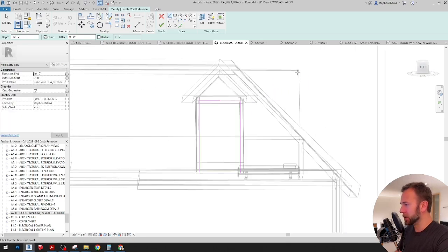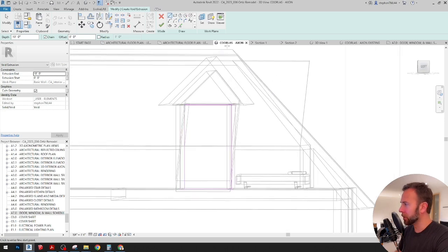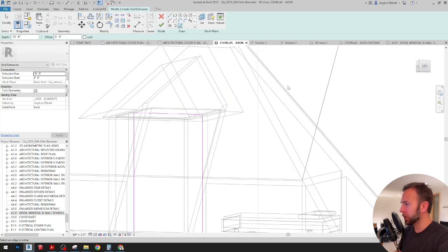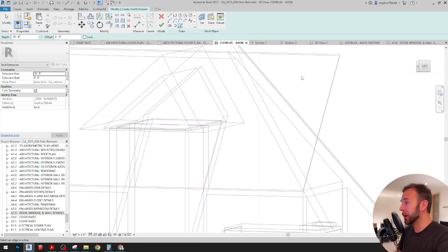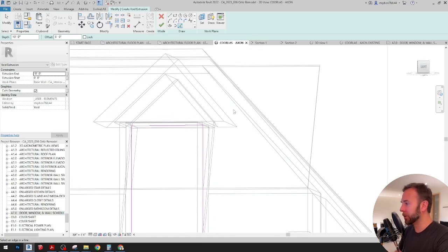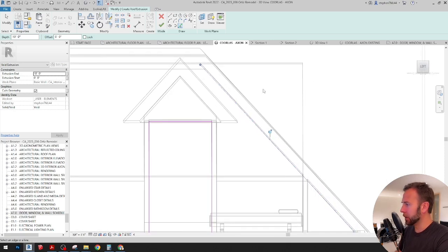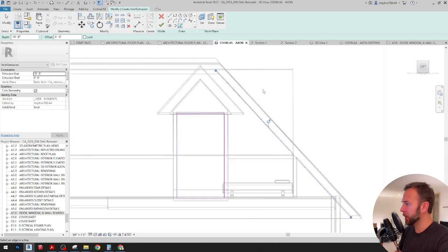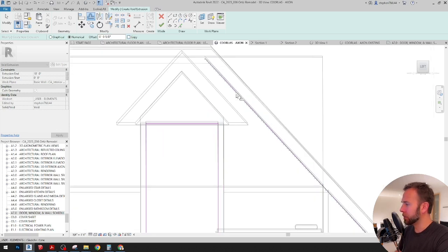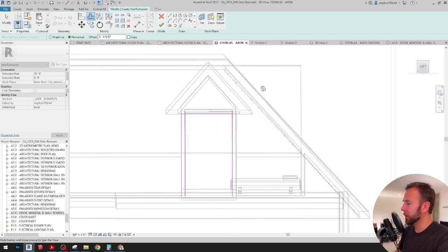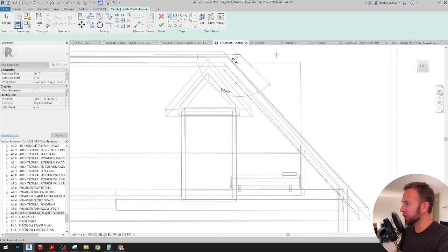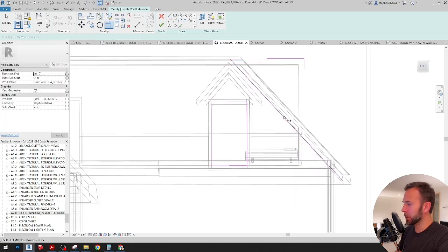And then same here, you can see this edge kind of flying out towards the side there. We're going to want to trim that, and we can take it either 5/8 of an inch, pull it back 5/8 of an inch to accommodate for this face that we'll need to do. And I think I will do that so it makes modeling that next one a little simpler. So 5/8 of an inch, do not copy, pull it back, and just to trim that whole corner basically off. We'll see what that looks like.